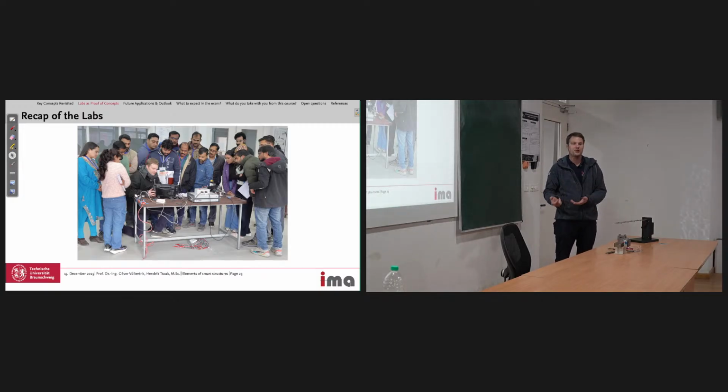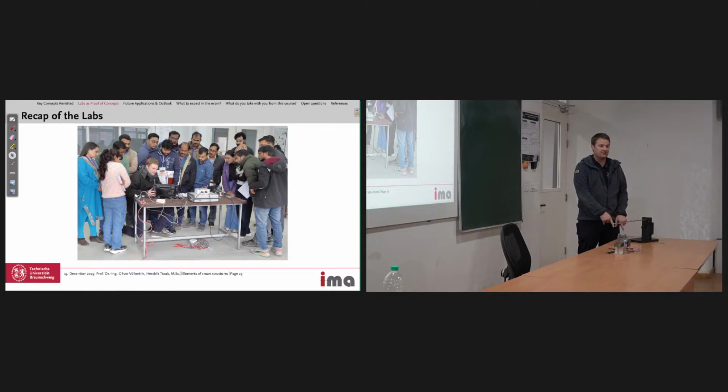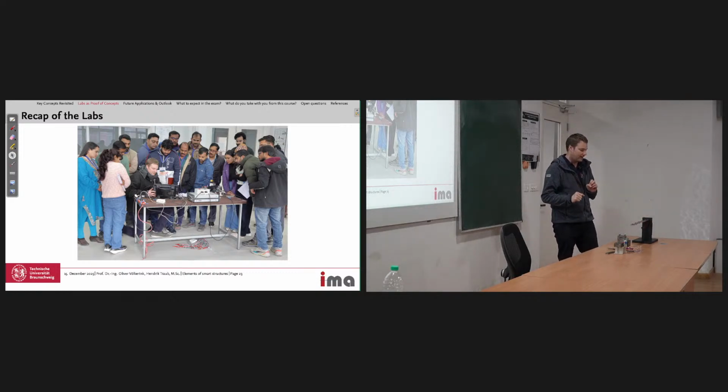And if you do it for yourself, then sometimes it makes a lot of sense to put another sensor on the clamping or on the desk even. So we had some experiments on a simplified wing model where we had a sensor here on the table and the wing here on the table, and everything was massive steel. But anyway, then we got some really terrible noise and we couldn't identify why, and then we had to look at the table, and then it was clear that some vibrations went through the table into the sensor.